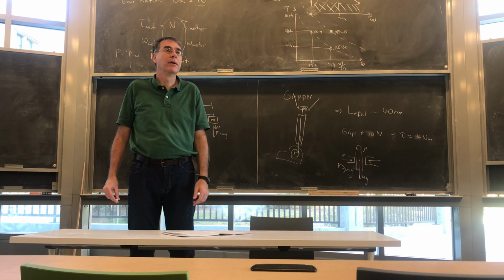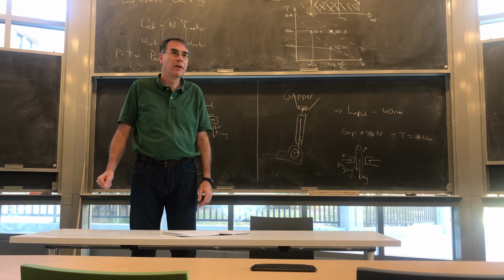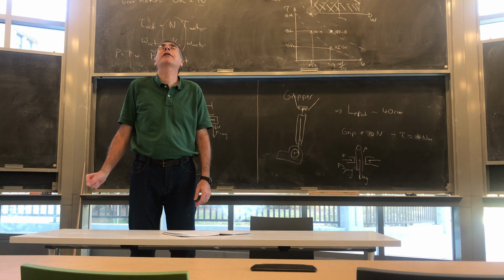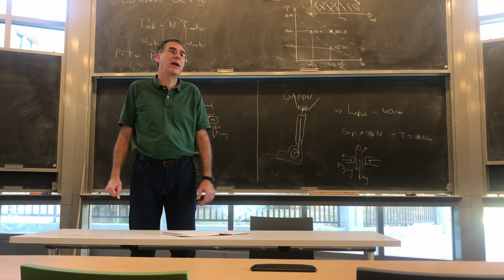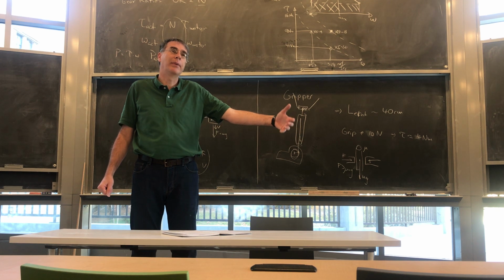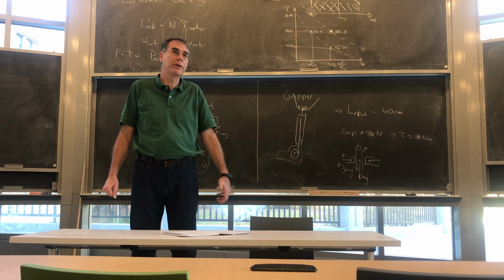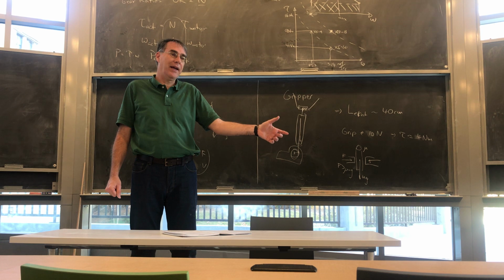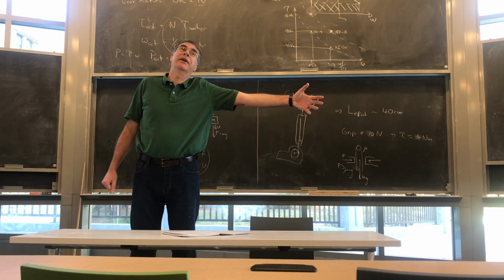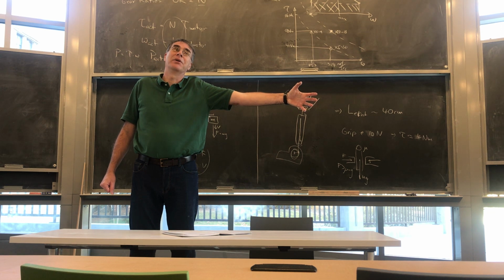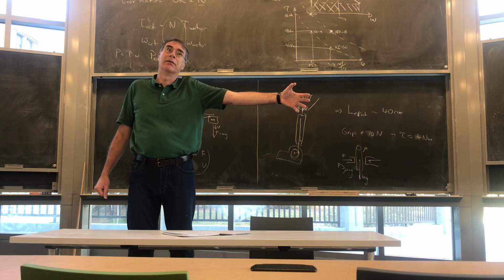How heavy are the heavies? The X5s, I think, are 350 grams. The X8s, I think, are 500 grams. I'm assuming that we're not going to fly the X8s out there, so I assume it's about 300 grams per motor. If you build a 3-dot wrist and you want to stick it a meter out there, you're looking at about 1 kilogram out there already.